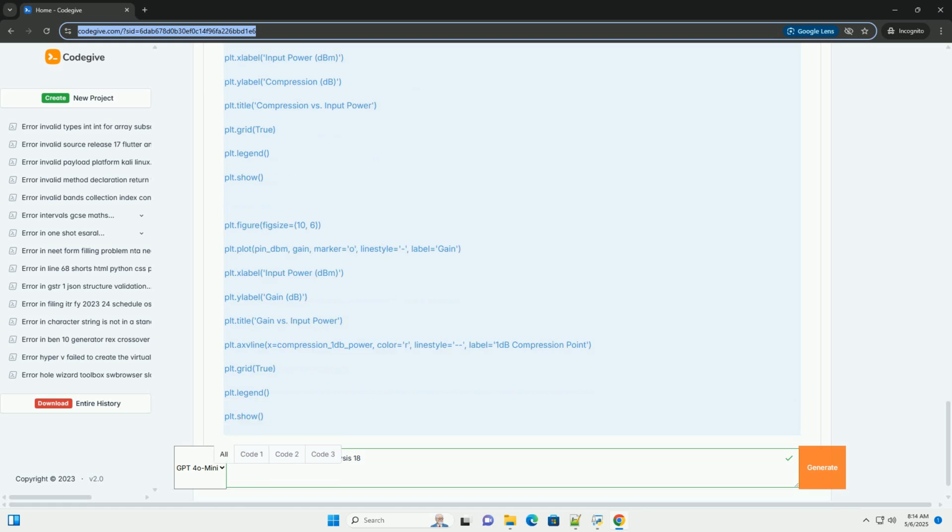Important considerations. Units: always be consistent with your units, dBm, watts, etc. Simulation time: transient simulations for power scaling can be time-consuming, especially at low frequencies. Ensure you're simulating for a sufficiently long time to reach steady state. Simulator documentation: consult the documentation for your specific simulator for guidance on power scaling analysis, convergence settings, and model limitations.